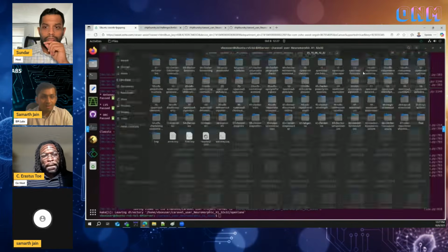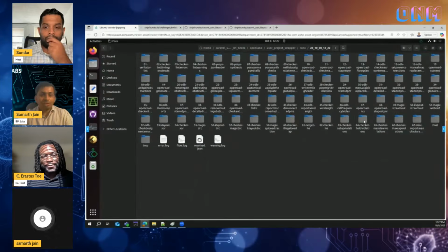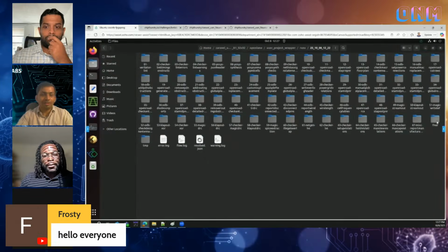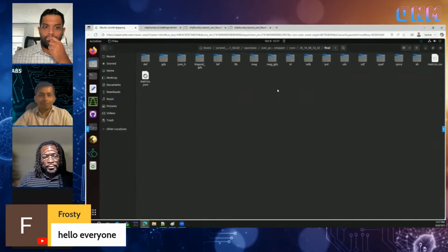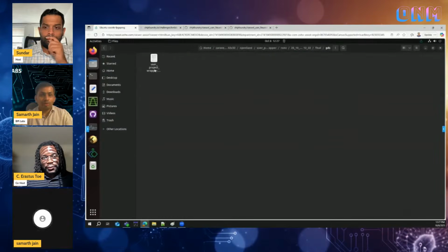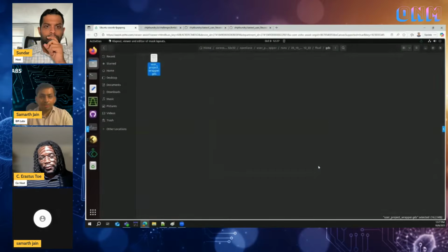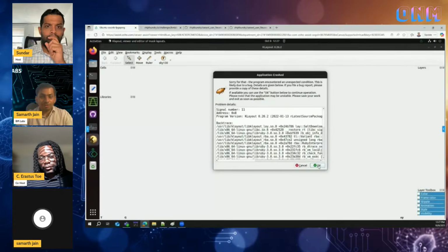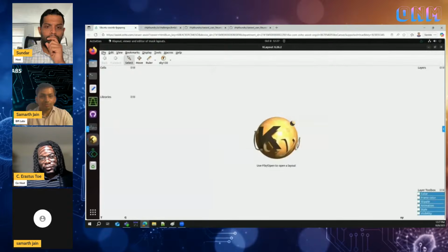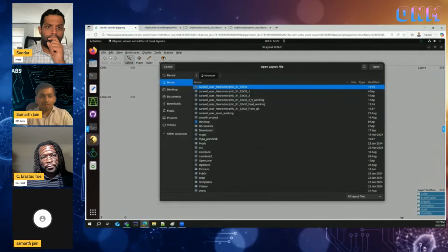you can see the process has been finished and we have all the checks clear, which is antenna clear, LVS clear, and design rule clear. So finally we can see the GDS which goes to the foundry, the factory, right? So this tool will generate the file which goes to the factory, which you can just submit to the MPW runs via partners, and it can just go to the factory. So we'll try to import that GDS, which is generated by OpenLane, in KLayout to view it.